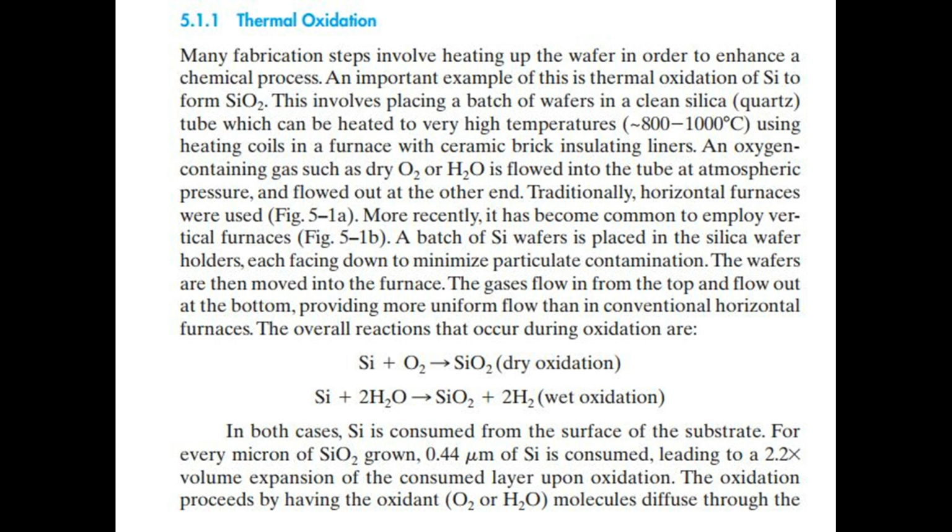Si + 2H2O → SiO2 + 2H2, wet oxidation. In both cases, silicon is consumed from the surface of the substrate. For every micron of silicon dioxide grown, 0.44 micrometers of silicon is consumed, leading to a 2.2 times volume expansion of the consumed layer upon oxidation.